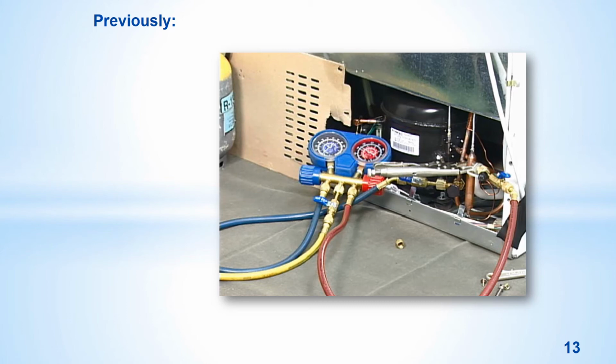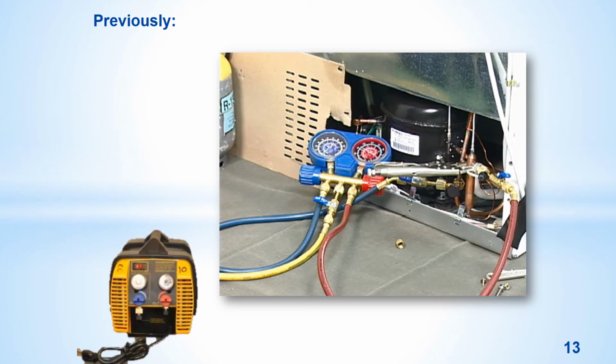In the previous video, the refrigerant was recovered from the product. The next step depends on the situation. In our scenario, it was determined that a high side leak caused the seal system failure, and if unsuccessful in locating a leak with the existing refrigerant pressure, the refrigerant is recovered and then nitrogen added. The reason nitrogen is the next step is that the maximum safe system pressure can easily be obtained compared to the existing refrigerant pressure, and the leak is then likely found.